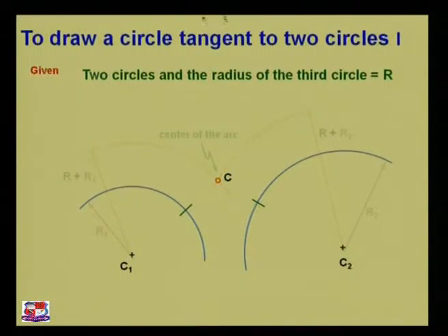What have I achieved? I have achieved two tangential points to this circle. I have got my circle center point, I have got the radius. Now the next step is I need to draw an arc using the compass like this, with radius r. The same distance we have put up over here, the same distance will cover over here.